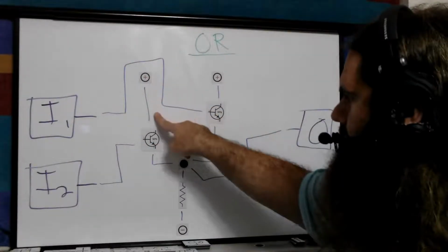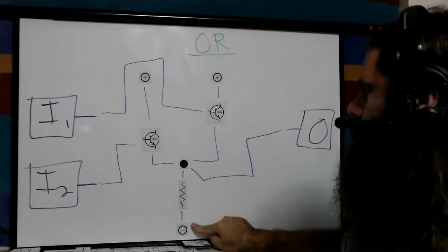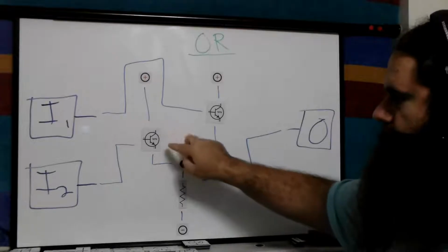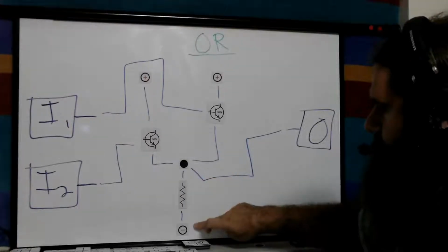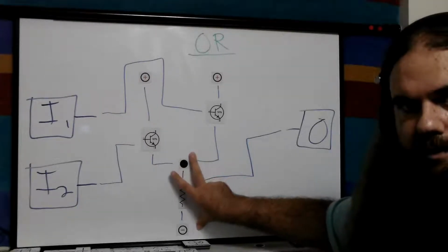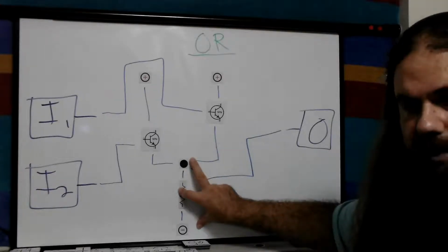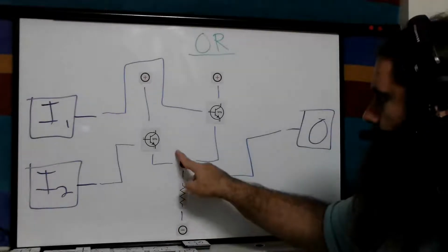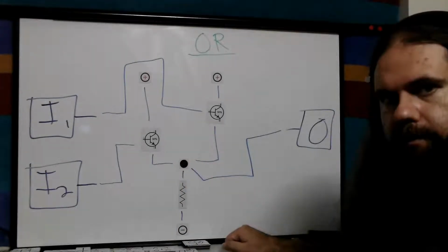So now I've got power through the transistor and there. So we've got 5 volts here. Let's say 0.2 volts through the transistor, so 4.8. We got 0 volts here. So we've got 4.8 here, 0 here, and the resistor is taking the rest because it is conducting now. We're sampling between the transistor and the resistor. So we're getting 4.8 here, and the output is high.